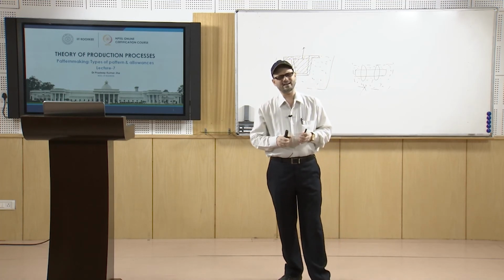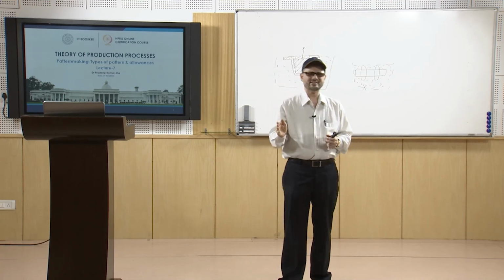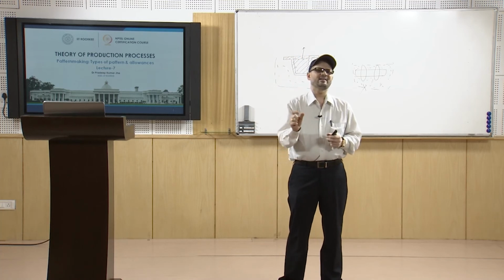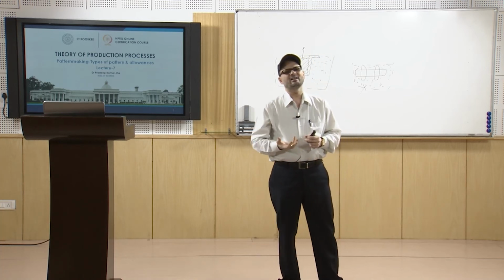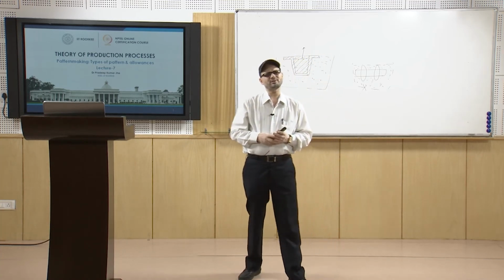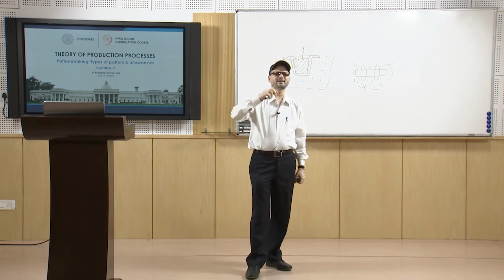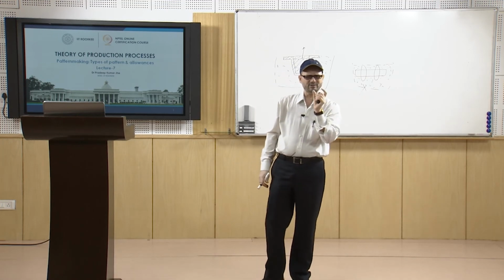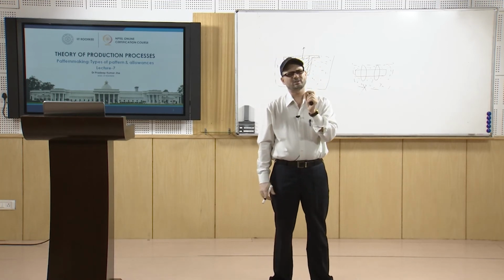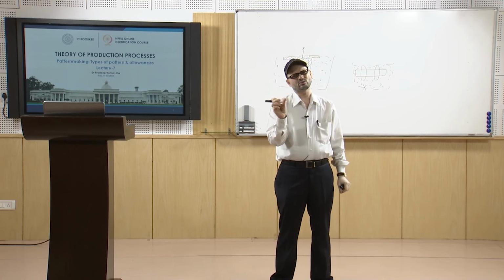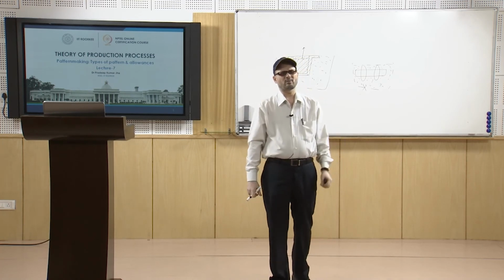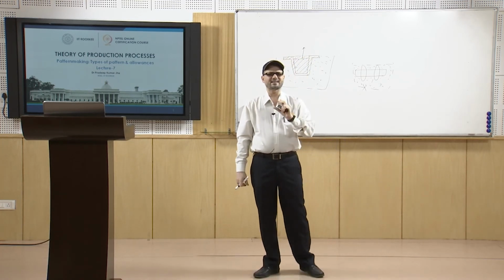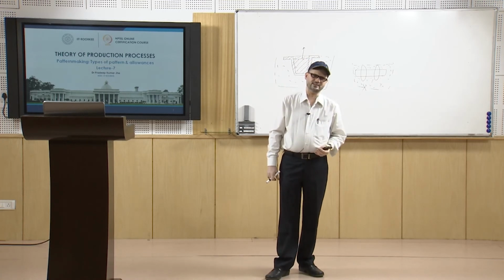Once you shake it laterally, the size becomes a little larger. So, in this case you give a negative allowance. You normally make the cavity a little smaller, because you know that you are going to shake and wrap it, and it becomes a little bit oversized.